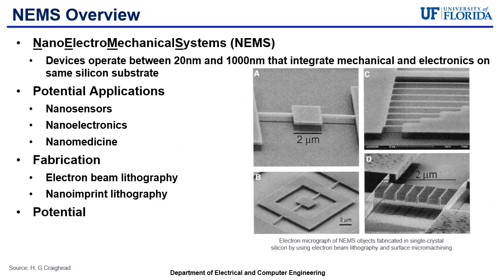Moving forward onto a brief overview of NEMS technology. It is very similar to MEMS technology. The biggest difference is that NEMS stands for Nanoelectromechanical Systems, due to NEMS technology operating on a nanoscopic scale rather than a microscopic scale. This makes NEMS technology operate on a smaller scale than MEMS technology by an order of 3 magnitudes. NEMS technology is still being developed, but they have a wide range of potential applications, ranging from nanosensors and nanoelectronics to nanomedicine. And because of their even smaller scale, fabrication of these devices requires specialized manufacturing techniques, such as electron beam lithography and nanoimprint lithography.